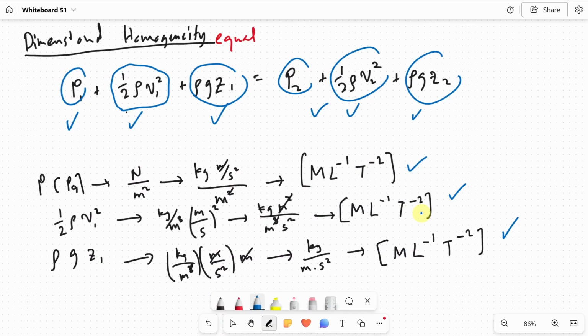So when you are doing any analysis and you find yourself in a position to add two quantities, such as this one, we have 3 terms on each side, and you see that they have different dimensions or different units, it means that you did something wrong at the earlier stages of your analysis. So you have to check your dimension.